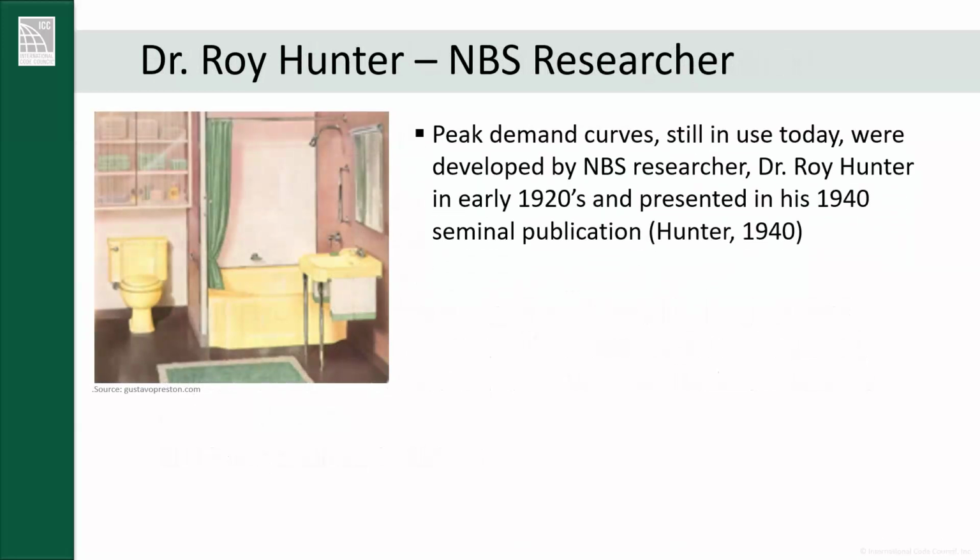Bureau of Standards at the time, and he developed some demand curves, guessing what the probability of use of water and the fixtures in the home would be. And he started his work in the early 1920s, and then he finally published his work in the 1940 publication. So if we've heard of the Hunter curve and what's still commonly used today as a reference for coming up with pipe sizes, this was published in 1940, but it was actually developed in the 1920s.